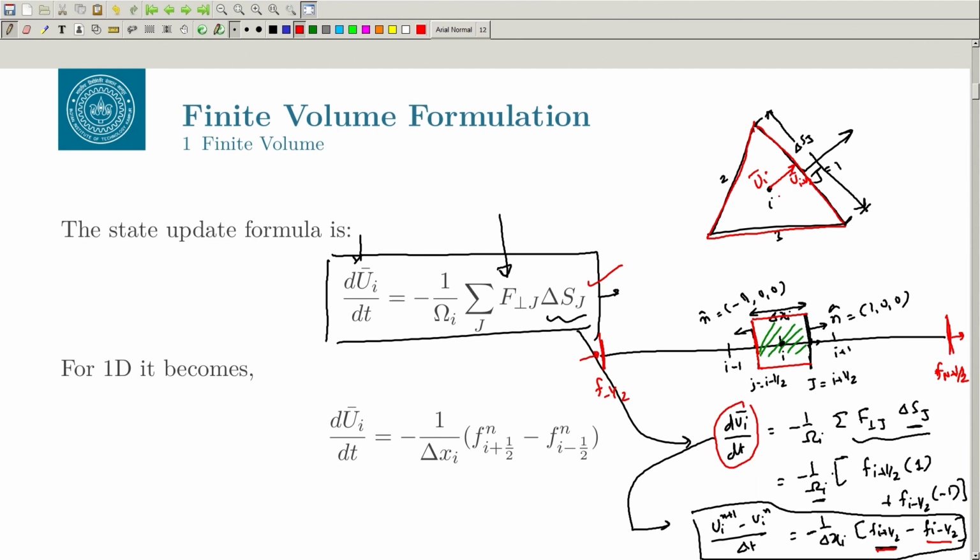Okay. So, if you know the cell gradient here from the linear variation, you can get the cell variation here, du I by dx, and du I, not the bar, only the variation of u. Okay. U I bar is the cell average value. Okay. So, this is du I by del y, and then if you know the variation, you can basically calculate the gradients at the faces. Okay. And from that gradient you can calculate the fluxes, right.